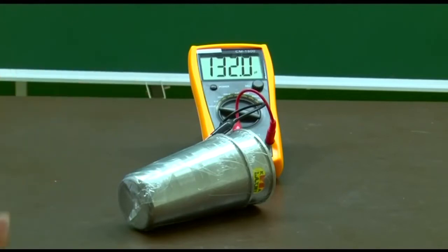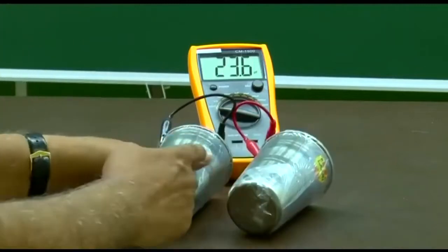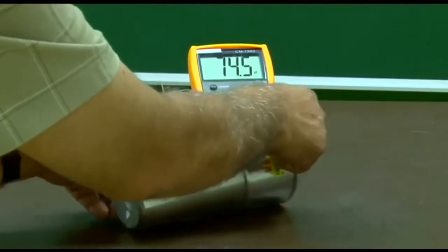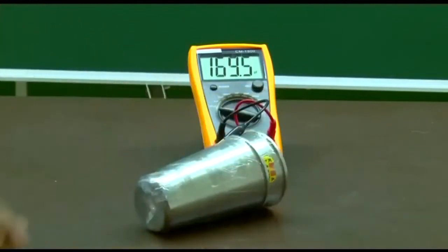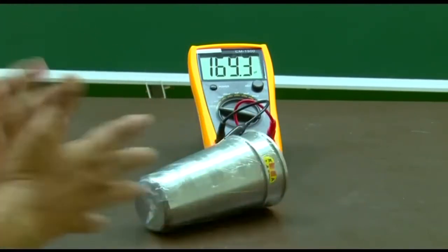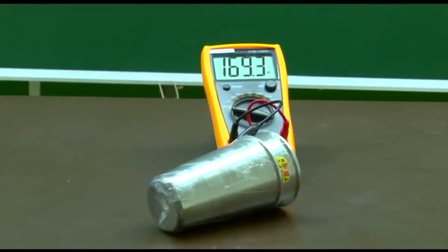So more and more area is in front of each other. That's the effective area. In fact, when I am putting it this way, the area which is facing each other is very small. When I am pushing it in, effectively the area facing each other is quite high. So your capacitance increases if the facing surface area is larger. And of course, the distance between the conductors, the average distance in whatever way you measure, is important.